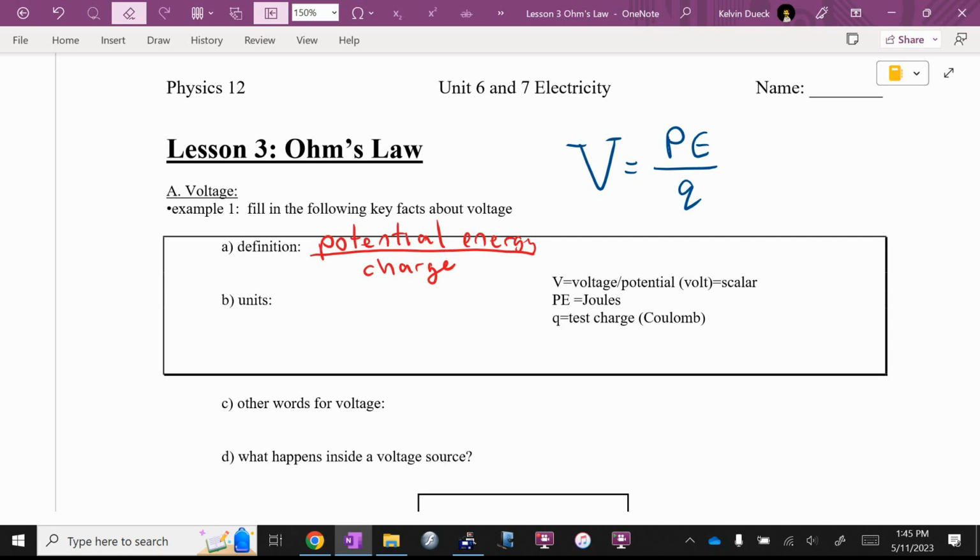That's an equation that I used to give people. It's one of the ones we crossed off the other day because I'm combining two units and shortening each one of them. But voltage is how much energy every coulomb of charge possesses. And so units, well, it's technically joules per coulomb. But this is so important, we give this a name. We call it volts. If something has 1 volt, what that means is every coulomb of charge passing through that object can give off 1 joule of potential energy, and you can do something with that energy.